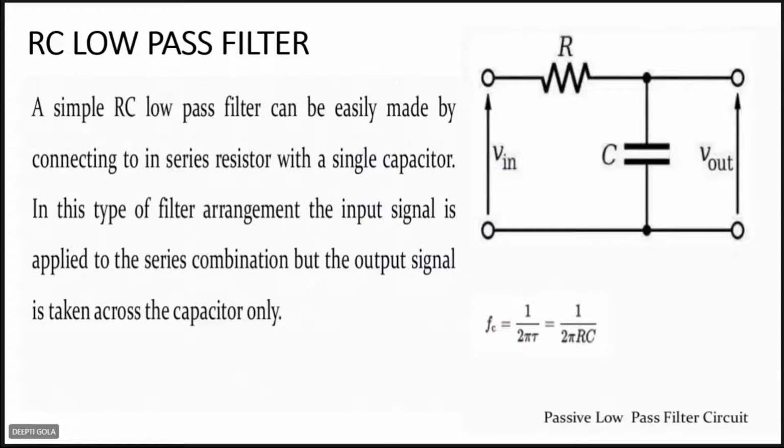Similarly, in the low pass circuit, what happens when the frequencies are high? Sorry, for low frequencies, this capacitor will act as an open circuit, right? So whatever input you are giving will appear at the output terminal.